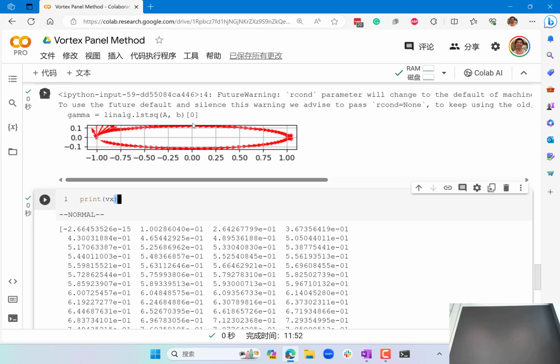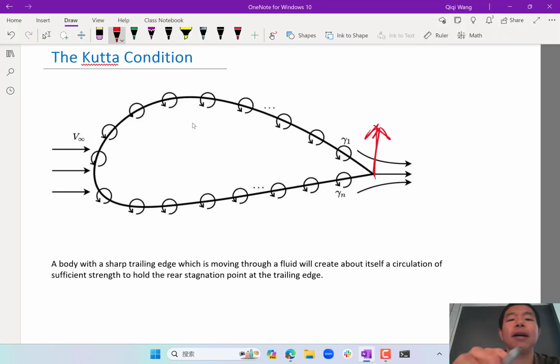The effect of that vortex is to make the velocity immediately inside the airfoil geometry be 0, right? So the opposite contribution should be added immediately outside of the airfoil. In this sense, the velocity just outside of the geometry is actually twice the velocity at the center of that vortex, right? So let me draw it a little bit more carefully.